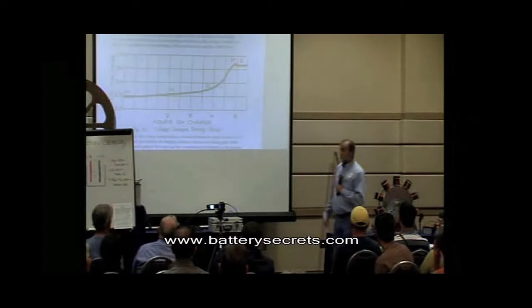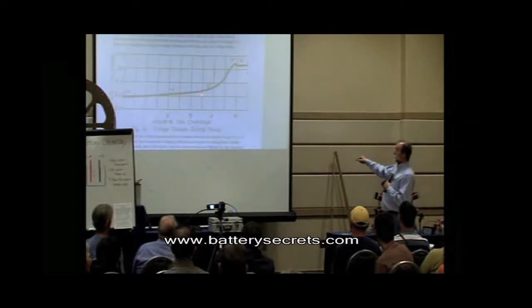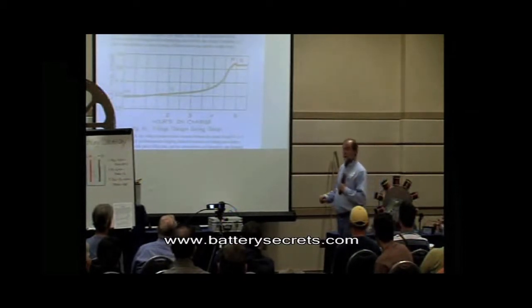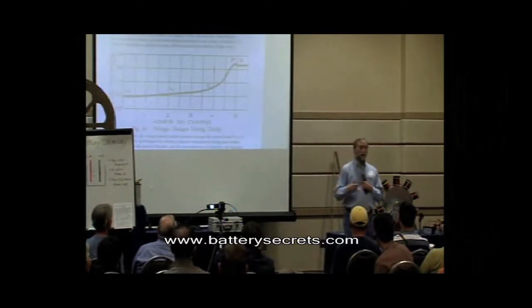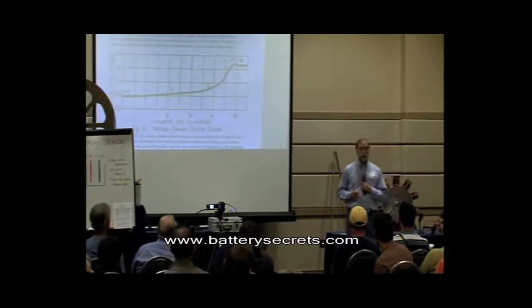And we started watching these things. And then it would rise, rise, rise, drop a little bit, and then continue to rise. You may have seen these things. What's happening there? What's happening is that the battery is chemically healing itself of internal layers of sulfation that have been unchallenged for a while.